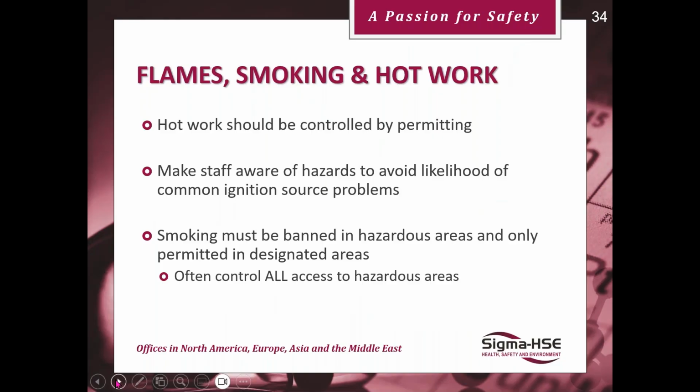Smoking must be banned in hazardous areas and only permitted in designated areas. Often control all access to hazardous areas. With regards to smoking, let's say within Europe, every site I go on today only allows it in a designated area, and some sites have banned it altogether. So we don't have this problem so much as we had 20 odd years ago.